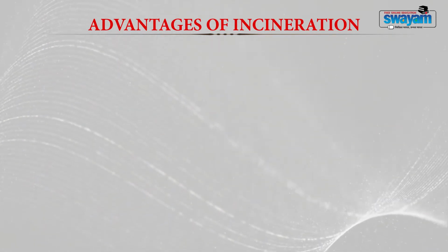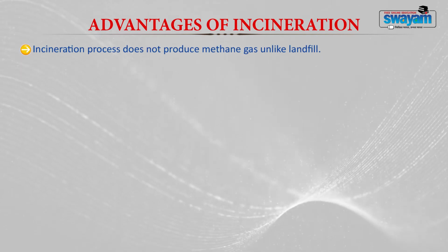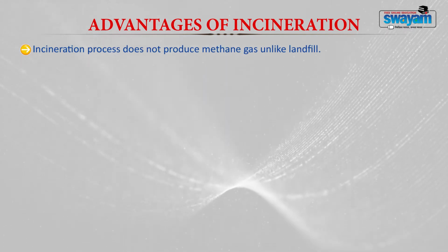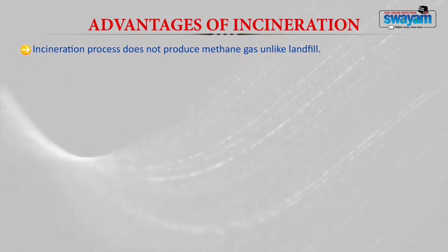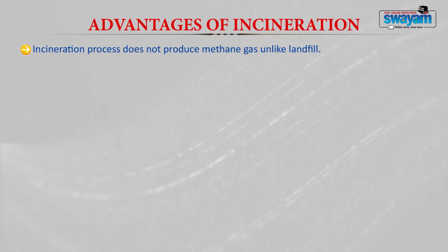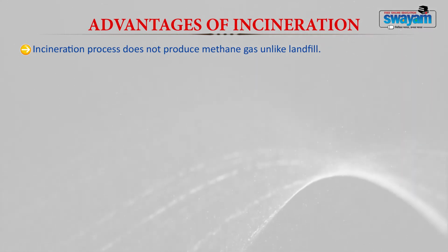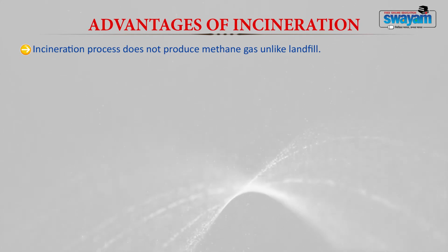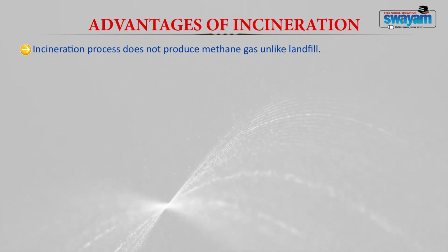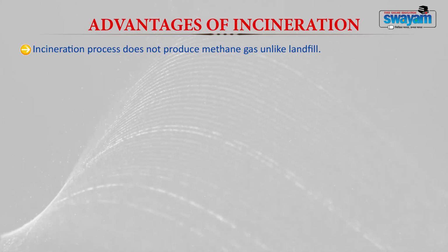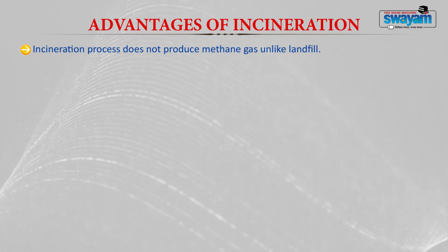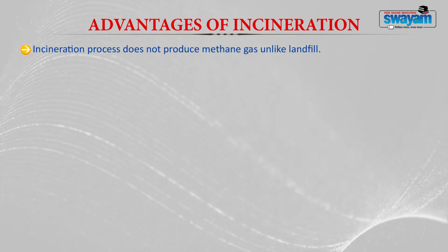The fourth advantage is that the incineration process does not produce methane gas unlike your landfill. In a landfill, during the waste degradation process, and in other biological conversion routes as well, certain gases are produced. These gases can be carbon monoxide and methane, all of which have global warming potential. In incineration, you do not have any production of methane, but carbon dioxide is produced.